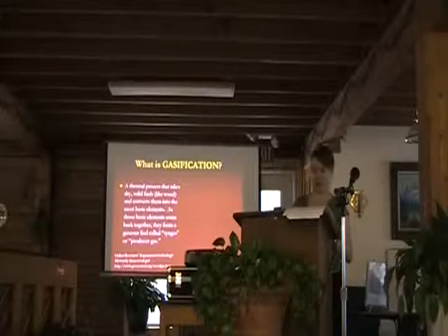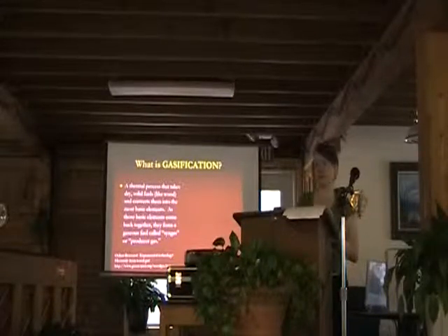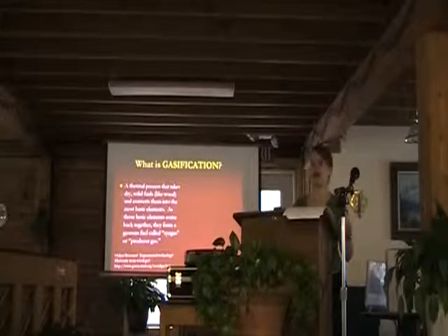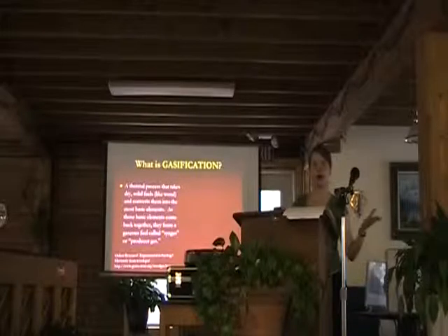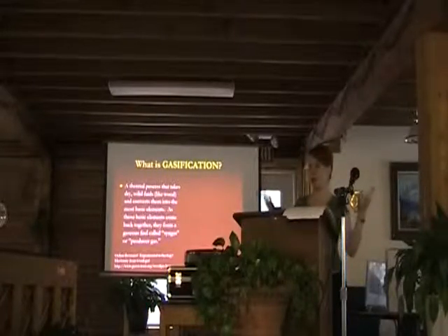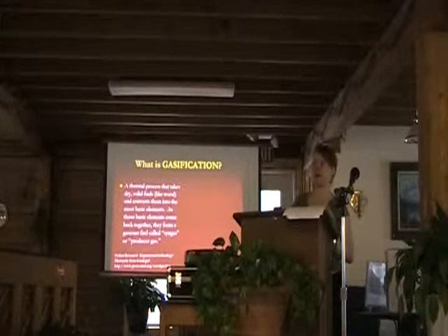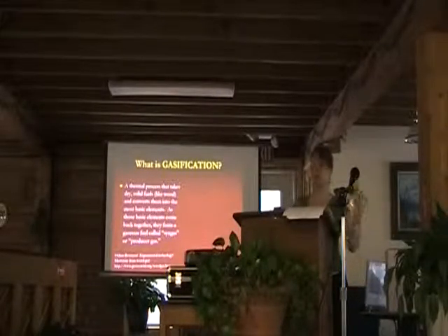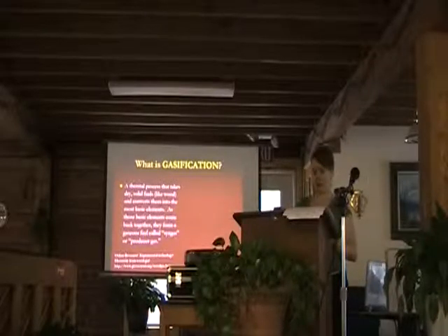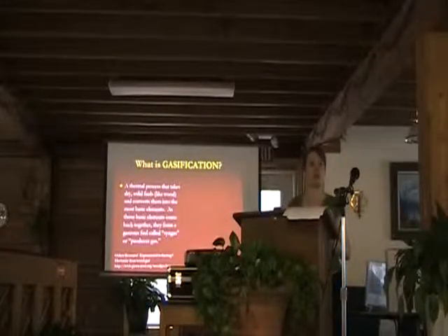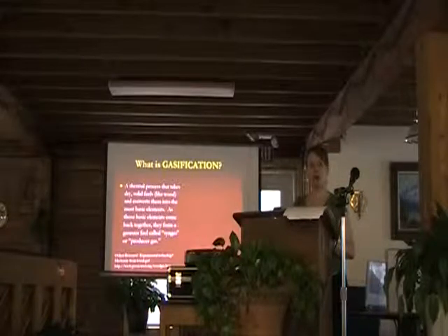And it burns more of the wood, and even burns the creosote, because as the creosote sticks to the sides of the boiler itself, when the boiler cools down at different intervals from usage, the creosote flakes off the sides of the boiler. And when the fire starts burning again, it burns the creosote that fell off. So it's very clean as far as creosote goes, and it's more efficient than direct combustion. And of course, direct combustion is what we use in our barrel stoves, in our wood cook stove.